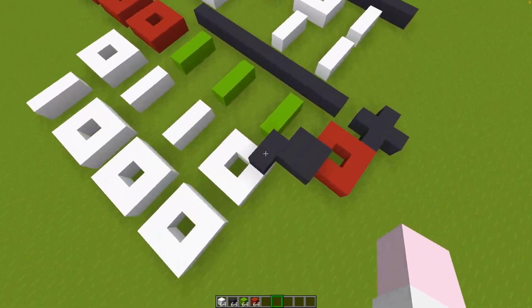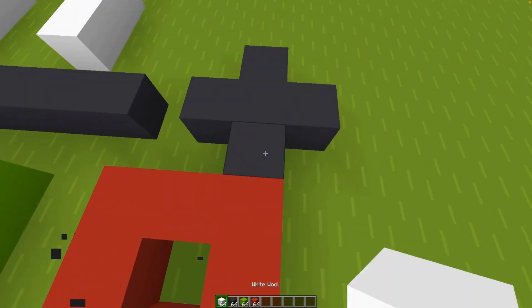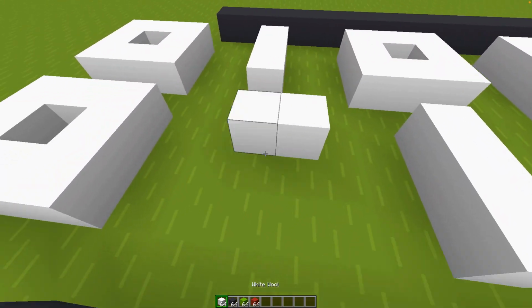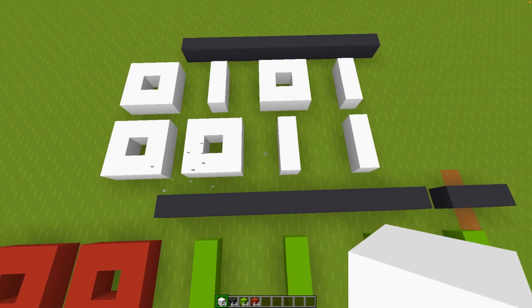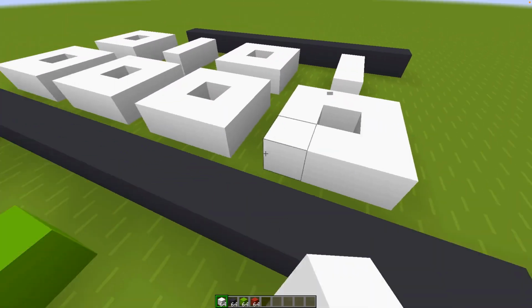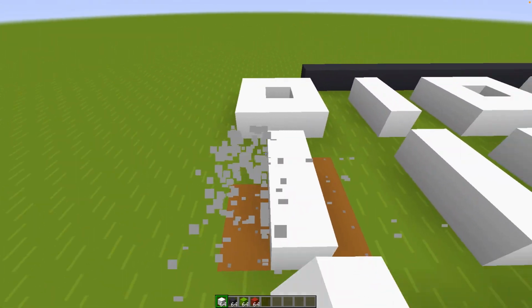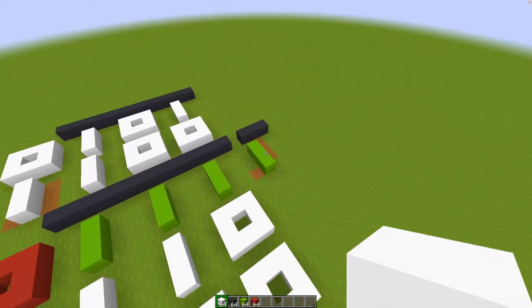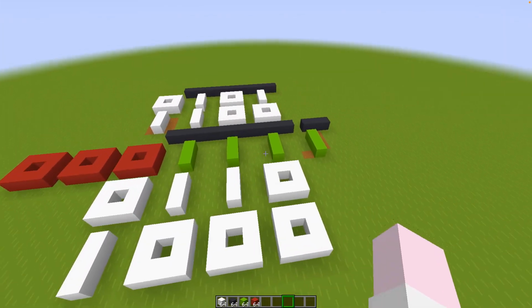Now I'm going to be showing off subtraction real quickly, and for that, this bit right here is going to be a 1. Now if I want to do 5 minus 3, then all you have to do is get 2's complement. So we first invert 3, which is 1's complement, but because the carry in is on, we already have 2's complement, so that was pretty easy. And then we just XOR again. However, the carry line is a little different.